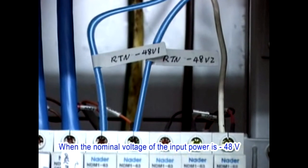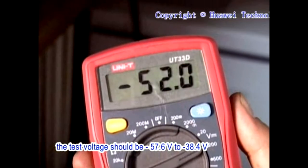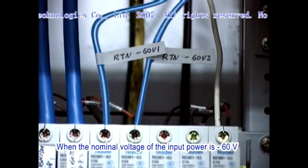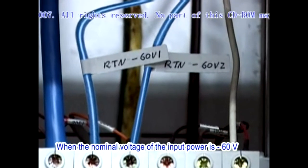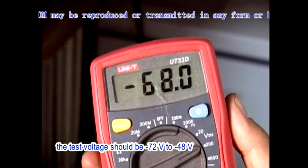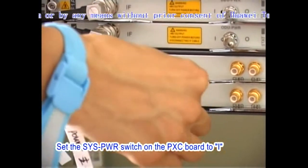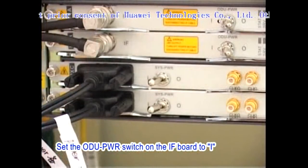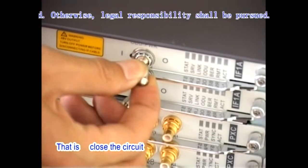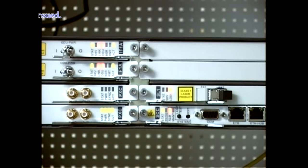When the nominal voltage of the input power is -48 V, the test voltage should be -57.6 to -38.4 V. When the nominal voltage of the input power is -60 V, the test voltage should be -72 to -48 V. Then turn on the input power. Set the system power switch on the PXC board to I. Set the ODU power switch on the IF board to I, that is, close the circuit. The equipment needs 3 to 5 minutes to fully start.